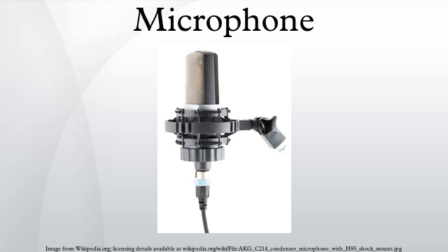One disadvantage of all windscreen types is that the microphone's high-frequency response is attenuated by a small amount, depending on the density of the protective layer. Beyond integral microphone windscreens, there are three broad classes of additional wind protection. Microphone covers. Microphone covers are often made of soft open-cell polyester or polyurethane foam because of the inexpensive, disposable nature of the foam. Optional windscreens are often available from the manufacturer and third parties.